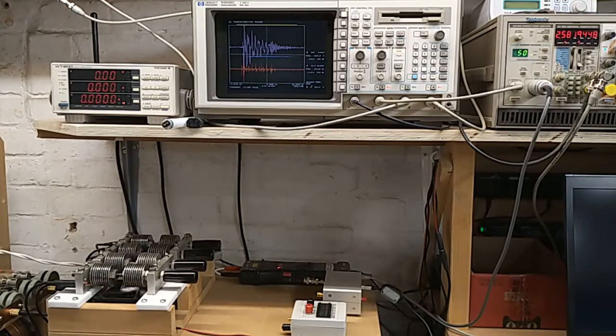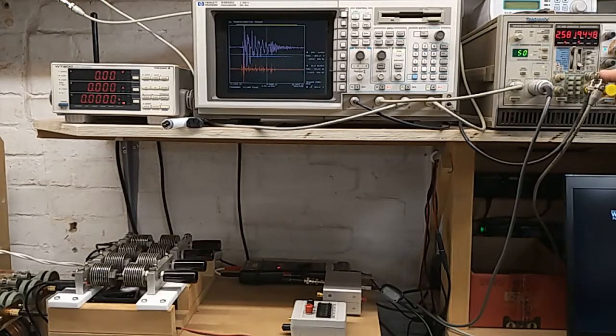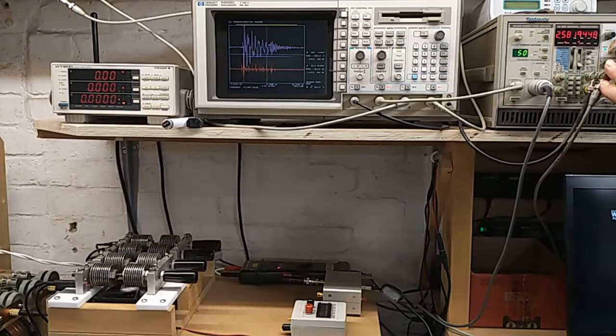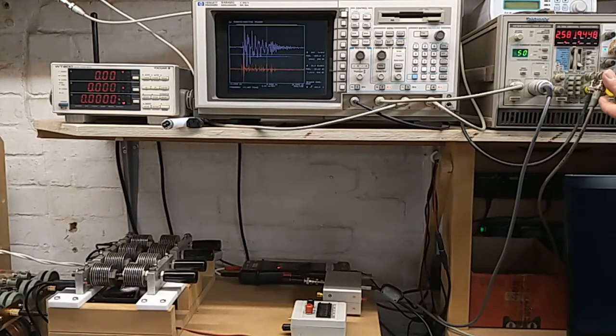So at the moment we're having a look at the normal instrument rack that we have. I did mention some of those items before, but we also have the frequency counter here that's connected to the high voltage probe that's connected across the input to the primary. This is set for a very high averaging, so it will give us a clearer indication of a central oscillating frequency.